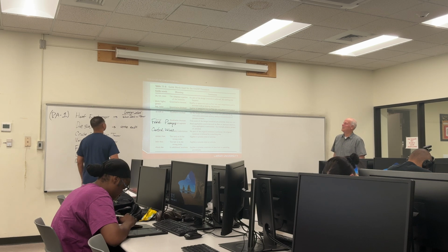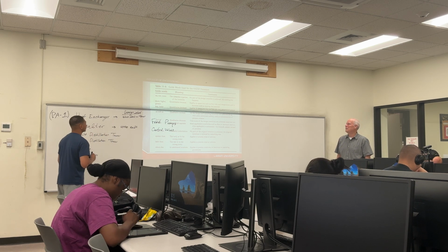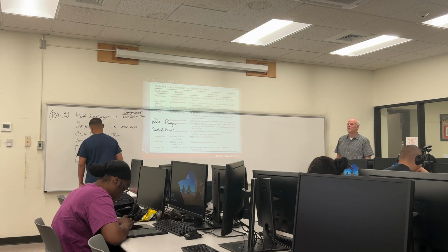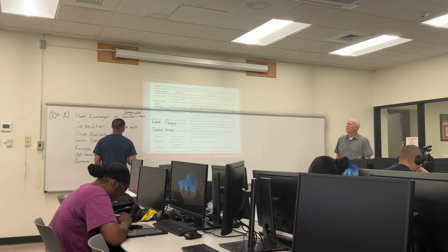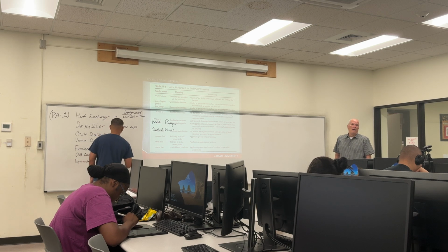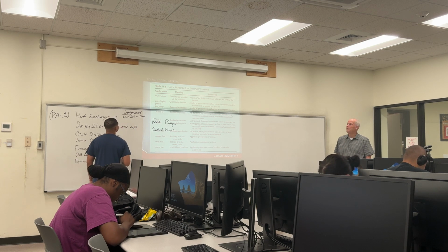What about the crude distillation tower? I mean, that's obvious, right? What do you have a tower for? What's the purpose of the furnace? To heat the bottom. You need to come up with a design intent. Why do we have a furnace? To heat the feed. It's more than just heat it, right? It's to vaporize it, isn't it?